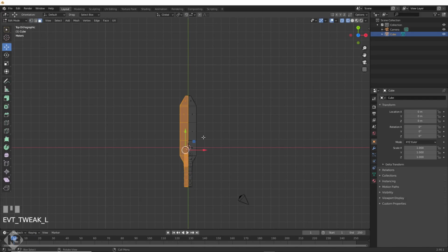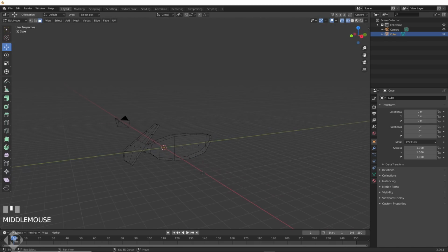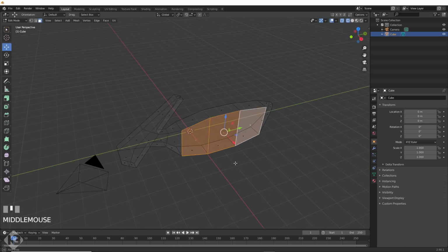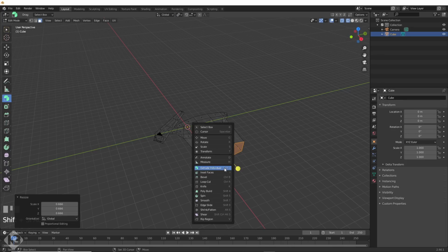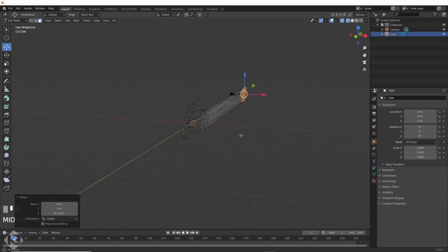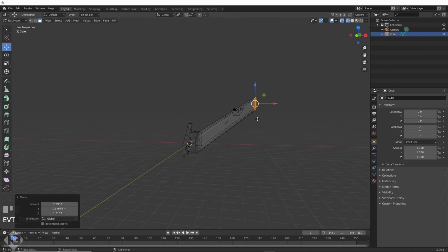At various points, I decided to delete half this thing, then add a mirror modifier from the modifiers panel. This allows you to work on one half while the other is just mirrored. Another cool trick I'm using here for the leg extrusions is setting individual origins. When I extrude and scale these parts, they will scale down by themselves, not together. Try it, you'll love it. Just remember that it's on when things don't work the way you're used to later.